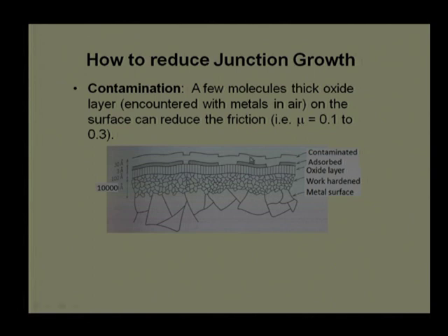In short, these layers decide the behavior of tribo surfaces. If all 3 or all 4 layers are removed from the surface, then we will get a very high coefficient of friction, and in fact it happens in soft materials like gold and indium. They do not get that many layers.